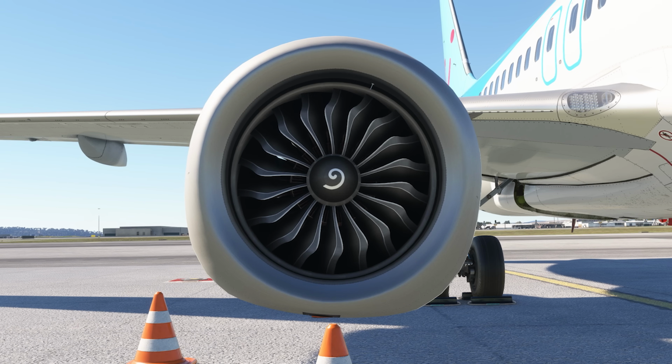We can't stay outside without mentioning these awesome new engines. These are the LEAP 1Bs, which replace the CFM56s, which were common on the NG. The fan blade diameter has increased from 61 to 69 inches, and the amount of thrust that it produces at sea level has increased to 27,000 pounds of thrust. I believe there's actually a higher thrust setting available from Boeing as well. These fan blades are made out of carbon fibre. They're incredibly efficient as well. I think it's a reduced fuel burn of around 15%.